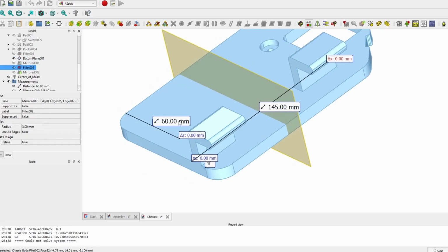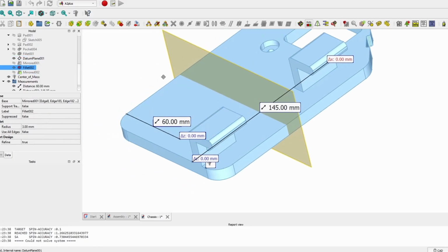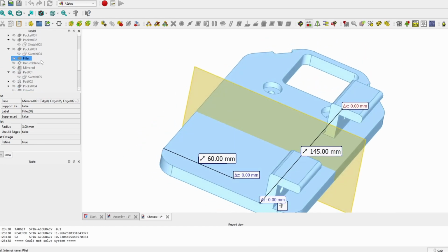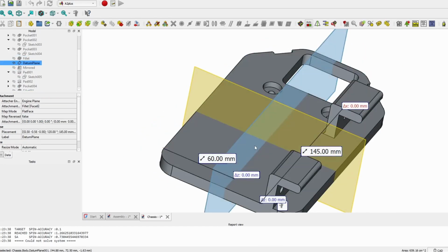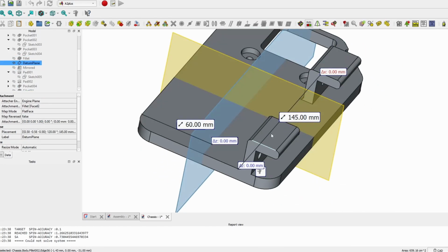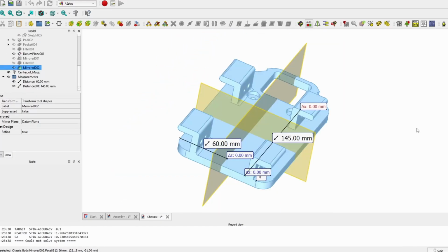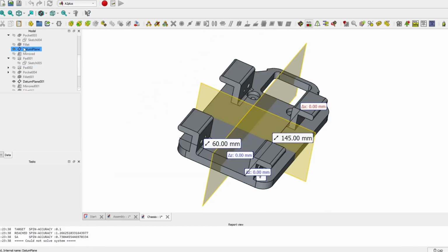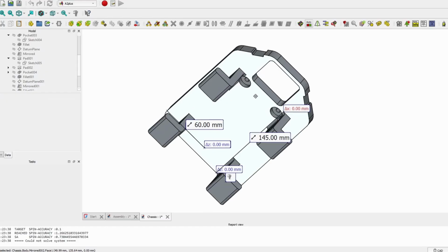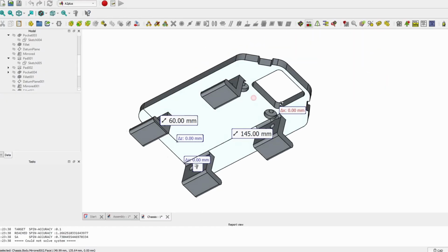And then we can fillet it like that. And then there's another datum plane somewhere. We use this datum plane to mirror these two features, to mirror over here. So the mirror of the mirror, I guess. Mirror image of the mirror image. Obviously, this takes a lot longer than just talking about it. That's essentially the concept of how you would make something like this.